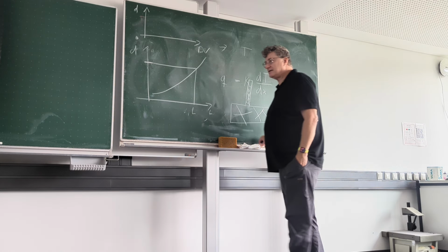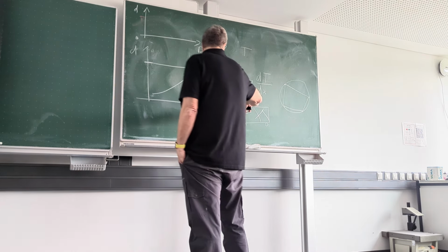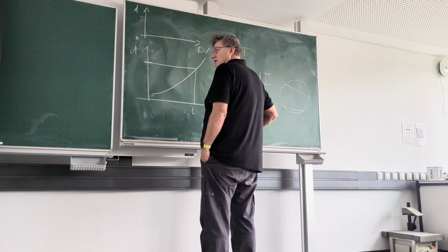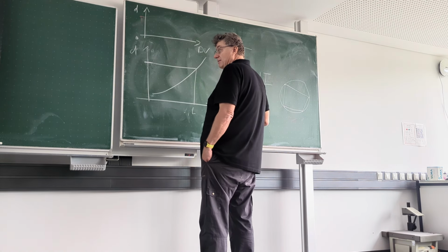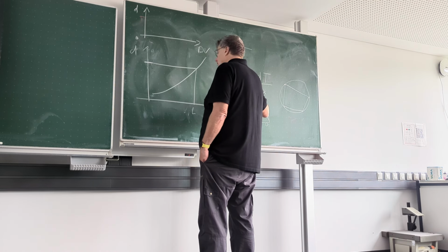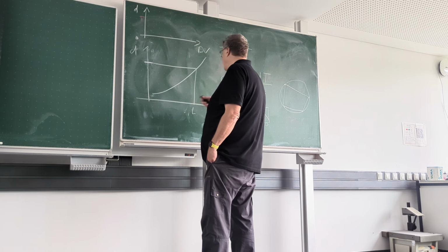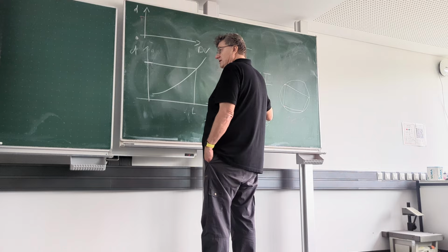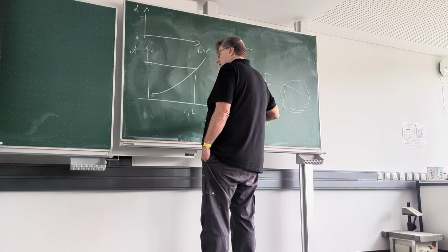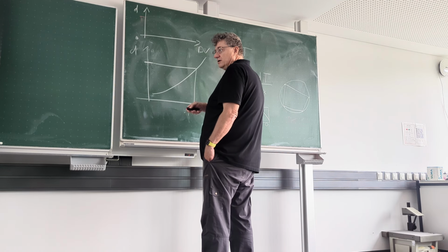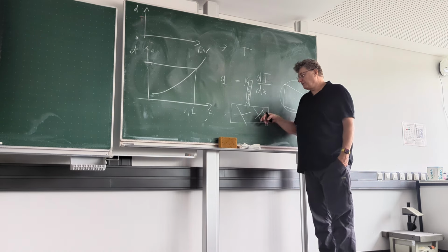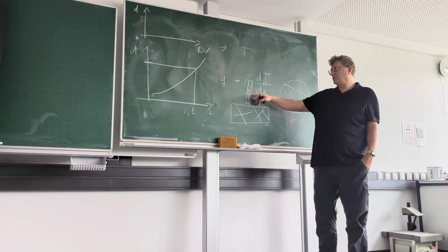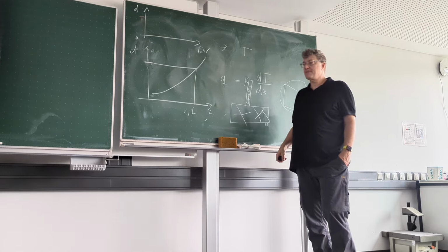And this again is something, here you have a more coarse mesh. The maximum coarseness is defined by the maximum element size. Here you are limited by the minimum element size, but in between, this parameter here, the resolution of narrow regions, gives the information how close you come to the minimum element size.